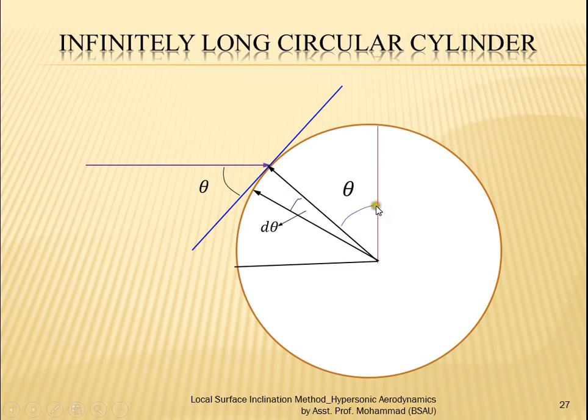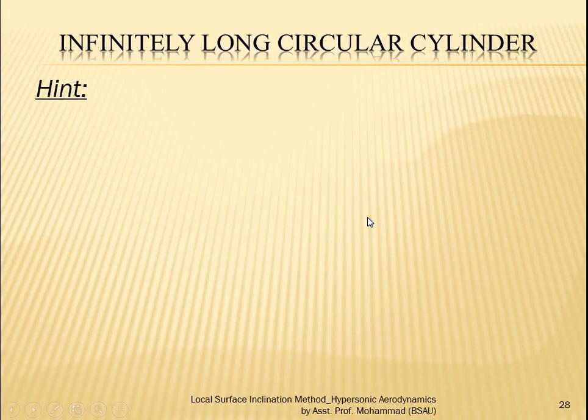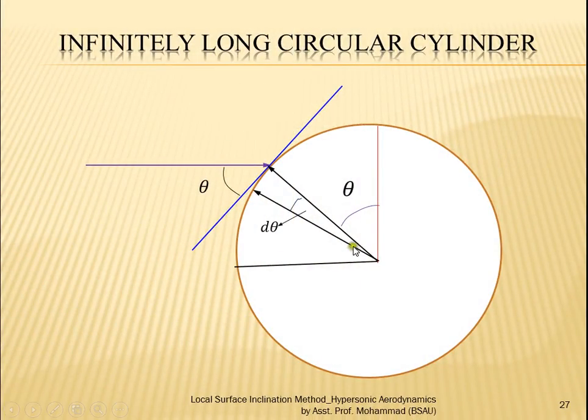This is the important thing we have to consider here. If r is here, the angle becomes 0. Then if r comes down here, the entire angle from here to here becomes pi. And we are not going to consider the other angle. We are considering the angle from here to here. Why? Because the location at which the flow will be attacking goes from the top position to the bottom position. This area will remain shielded, so the flow is not going to impinge on this area, and this angle will not come into the picture.